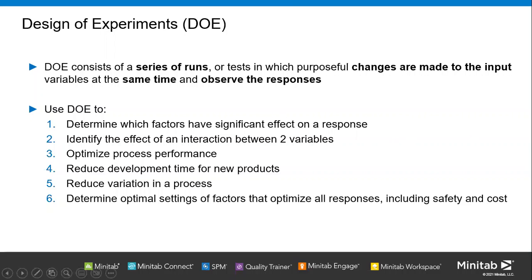And then in industry, design of experiment can be used to systematically investigate the process or product variables that affect the product quality. For example, just now I mentioned that after you define the process condition like stability and capability, then you can improve to enhance the quality and so on.